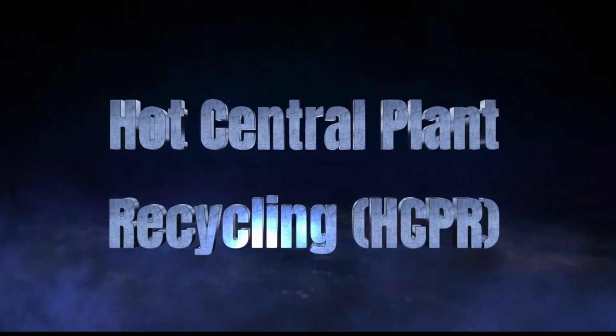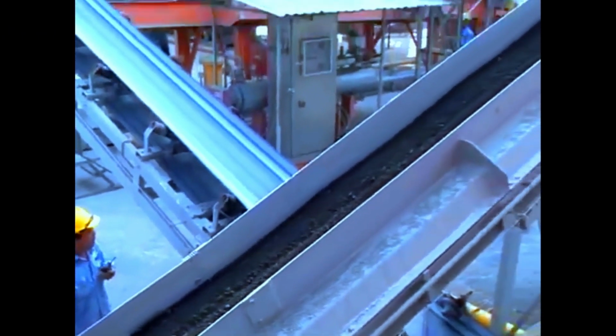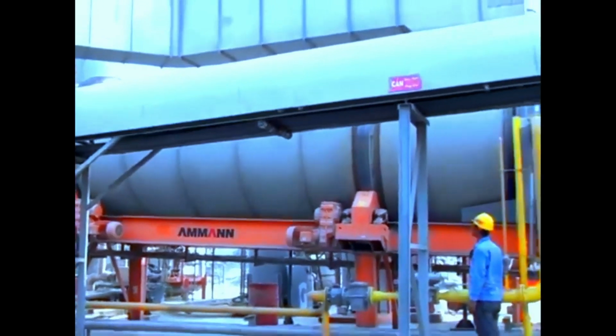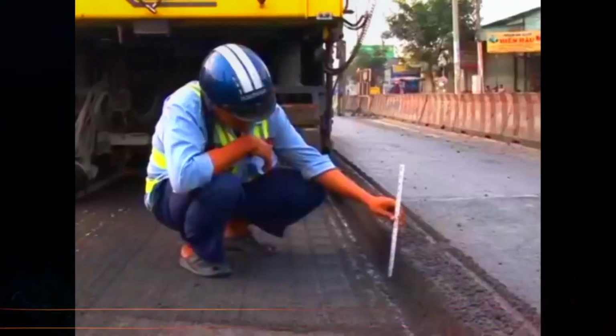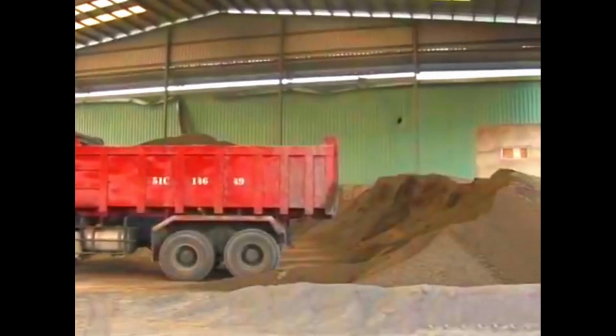Now the second method, hot central plant recycling, HCPR process. This hot recycling is also performed at an asphalt mixing plant for larger projects. This process involves: Step 1. Milling and transport. The top layer of asphalt is milled, collected, and transported to the plant.